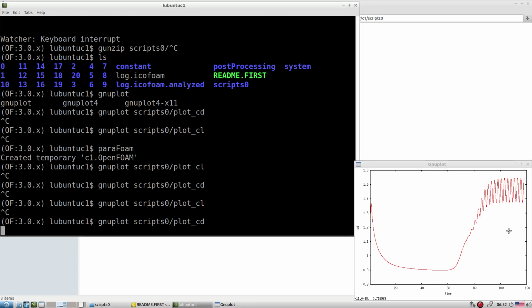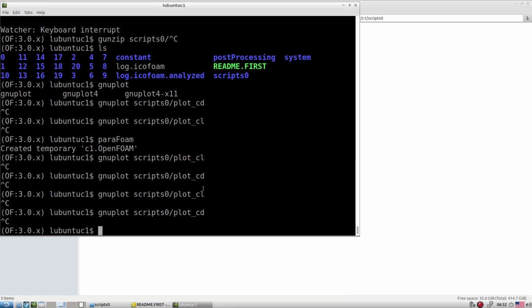Okay, so if this is the case, now you can stop the simulation. If you are only interested in the calculation of, let's say, the Strouhal number, then we have to open this in a different config, maybe Tecplot or so, with this data, and we can figure out the time lag between these repeated peaks. If we know the time, reverse the time, it gives you the frequency, and from that you calculate the Strouhal number and try to match it with the open literature.